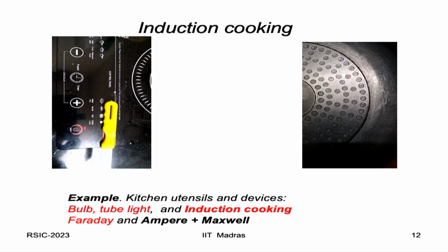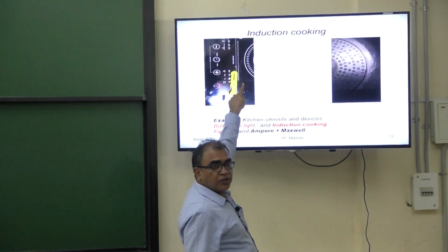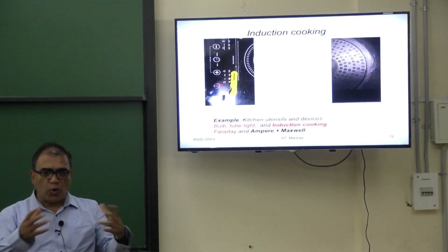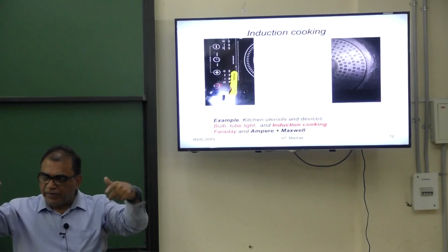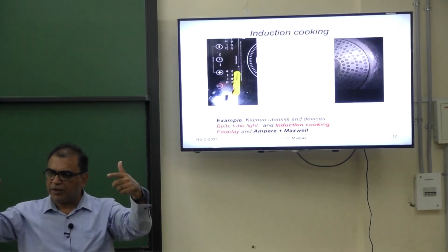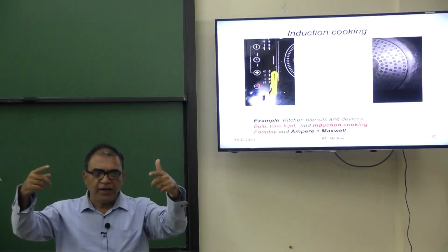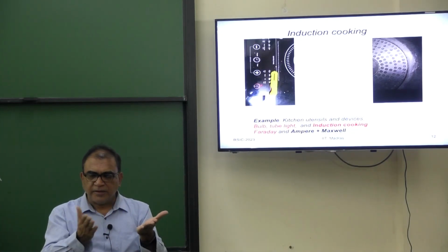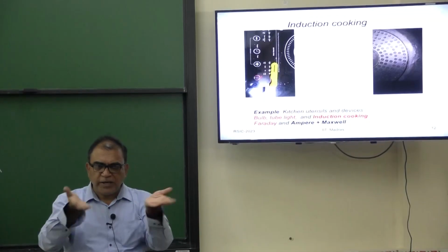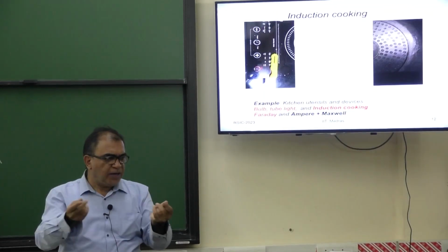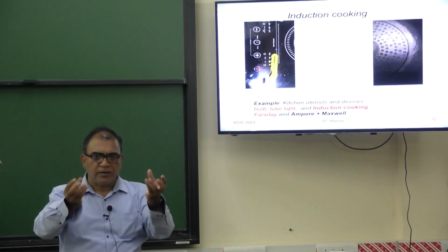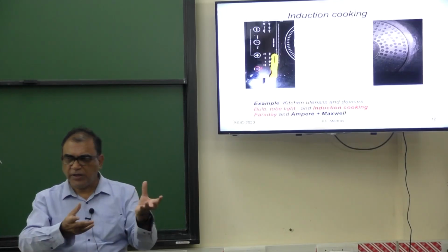So now that's what happens. You have an induction cooker with AC electricity, which has coils. It generates a magnetic field because a changing electric field can generate a magnetic field. The magnetic field now can induce currents in the ferromagnet, some eddy currents, and those eddy currents dissipate and make joule heating. That joule heating will heat the water and cook the food. Very quickly it is cooked.